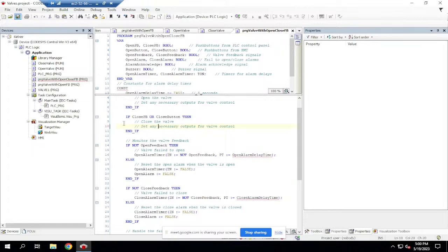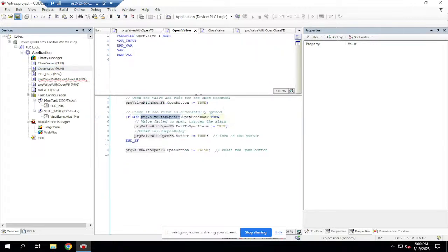So this is one use case why a function and function block need to be standardized with inputs and outputs, because we have not standardized the function and we are directly using other function block's variable or program block variable. It is not a standard function, it is just a function with variables linked to other blocks. A standard function will have variables with inputs and some outputs. Calculation is done using the input variable value, and then the output result is sent to the output variable.